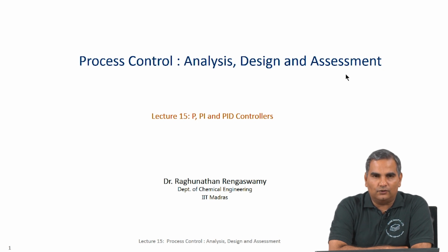And then we also saw that these are not objectives which are counter to each other, and we showed that if we take very large control actions, then you could have both the transfer function with respect to the set point going to 1 and the transfer function with respect to disturbances going close to 0.